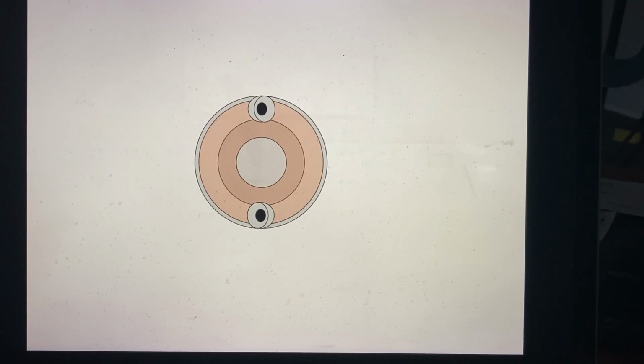Inside the combustion chamber, the rotation imparts a radial motion, effectively a pumping action, of the propellants into the main combustion chamber and through the injectors of the propellants, respectively the fuel and oxidizer. They're injected at high pressure into the combustion chamber, where again, as mentioned, they mix and burn to produce a hot, high-pressure working fluid, which emerges from the nozzles at an angle.